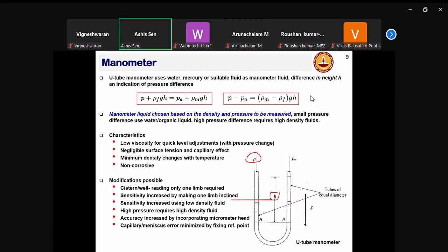That fluid has filled now here. So rho of fluid times g into H, that is the pressure at this level. And that should be equal to the atmospheric pressure here plus the manometric liquid. The manometric liquid and the source liquid have to be different. Okay, then only you will see an interface between them.